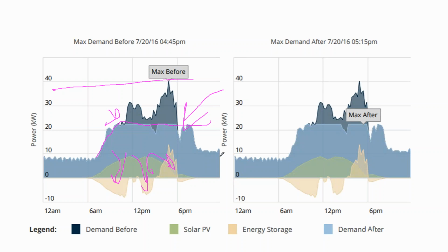You're at 208 3-phase, 480 3-phase, 240 volt 3-phase. So your voltage is fixed. And so you just need to monitor the power draw from the grid and say whenever you get more than 200 amps of power draw, turn on the battery bank to get this nice even fixed line.